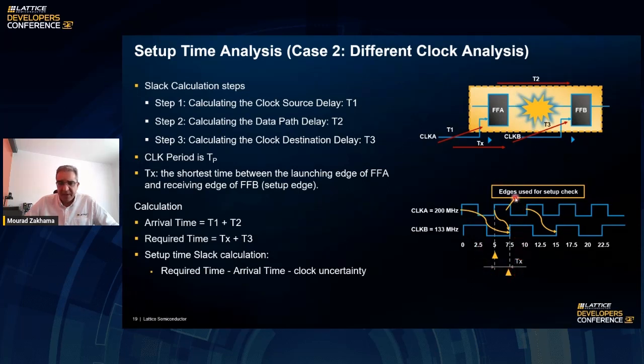That's the recommended way of dealing with clock domain crossing, making sure that you don't have any timing violation. In that case, you may want to tell the software that these paths going from clock domain A to clock domain B are false paths. That's where the timing constraint exception gets involved, just to make sure that the tool understands that you covered that by design and there is no need to analyze the clock domain crossing, just analyze clock A and clock B, for instance.